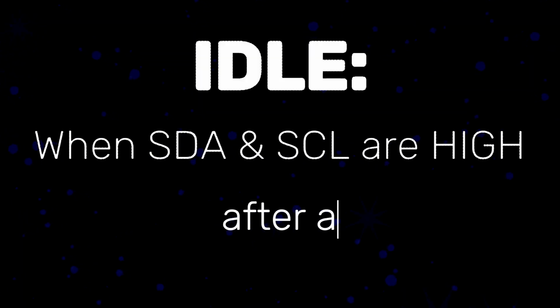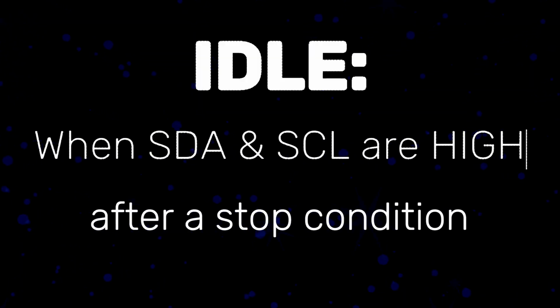Data transfers can only be initiated when the I2C bus is idle. The bus is considered idle when both the SDA and SCL lines are high after a stop condition. Because of this, a pull-up resistor is required so that both lines are high.